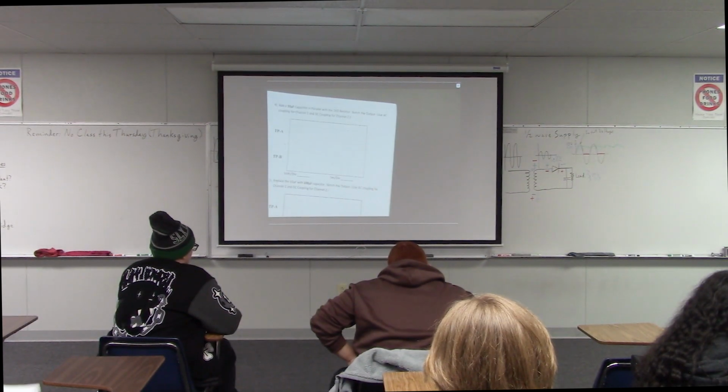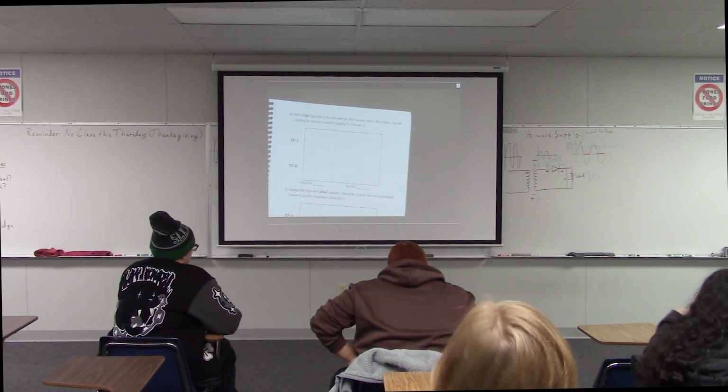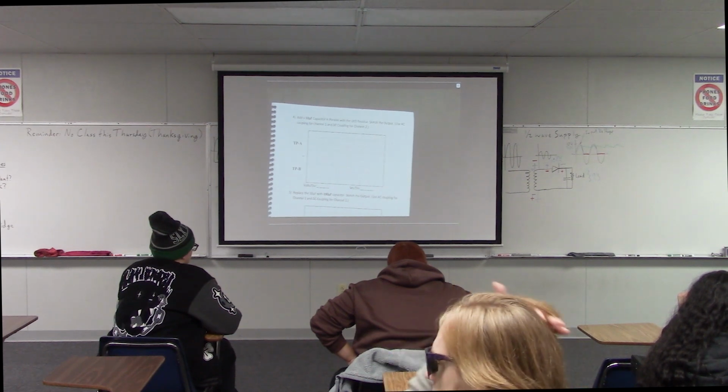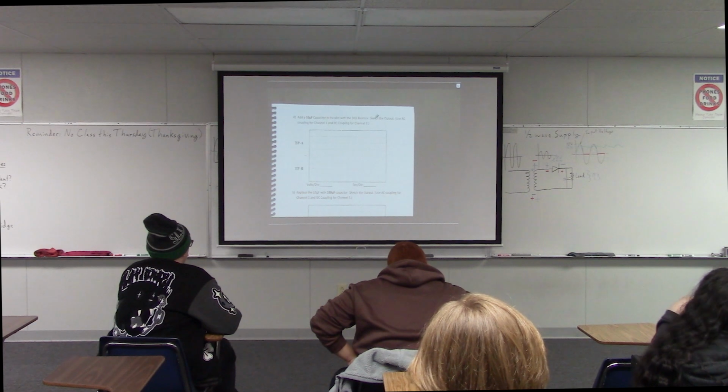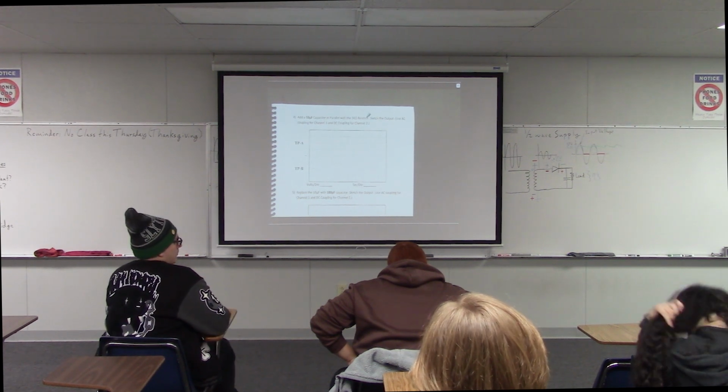And so then over here, you're going to add the 10 microfarad capacitor in parallel with the 1 kilo ohm resistor.